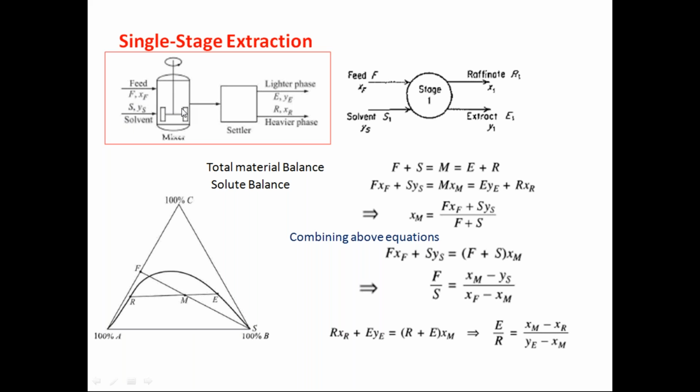In a continuous process, the feed will be sent continuously at a particular rate, and the solvent will also be added at a particular rate, and they will mix as they travel through the mixer. They form turbulence, and one will mix into the other very thoroughly. Then they will reach another settler, where decantation or centrifugation can be done to separate them.